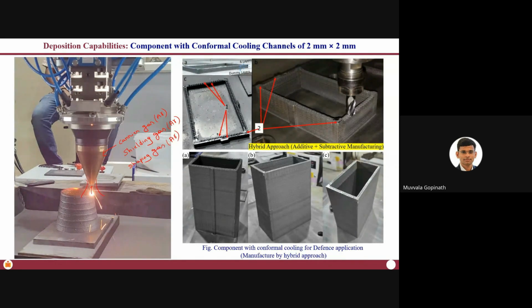When you take additively manufactured components, if it is made out of the SLA (stereolithography) process, typically the surfaces are relatively smooth. But if you are talking about metallic components, then the surfaces are not as smooth as you get in conventional manufacturing processes. If you look at a proper textbook, additive manufacturing is defined as a near net shaping process. What do you mean by near net shaping process? It will give the component a shape near to the final one, but it is not the final one. So first we have to understand that.